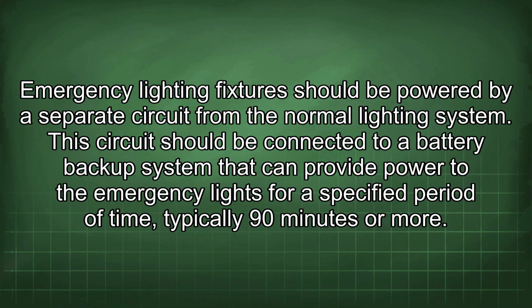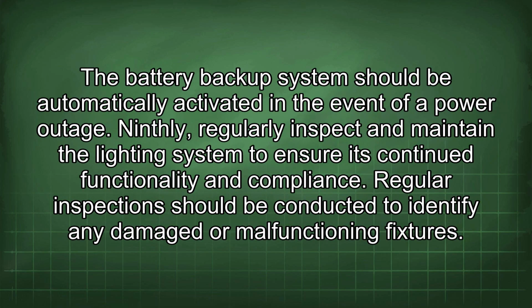This circuit should be connected to a battery backup system that can provide power to the emergency lights for a specified period of time, typically 90 minutes or more. The battery backup system should be automatically activated in the event of a power outage.